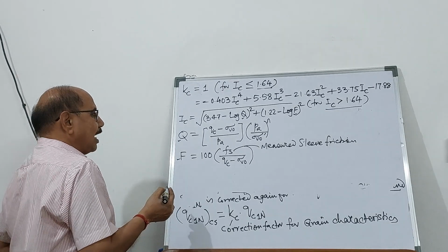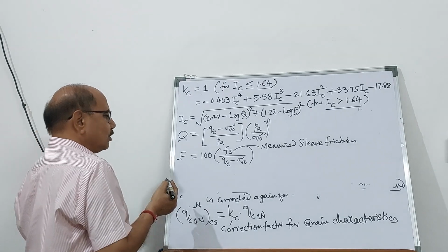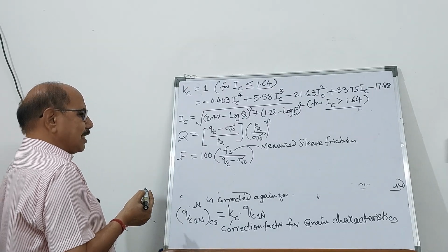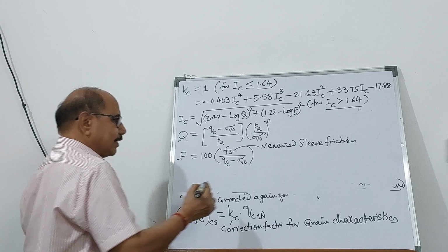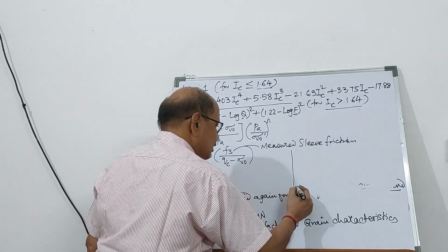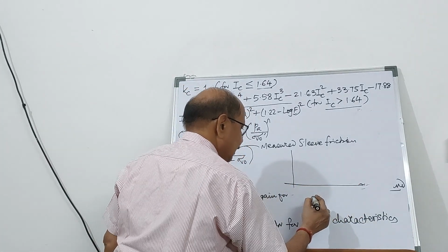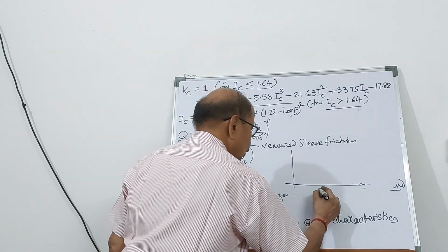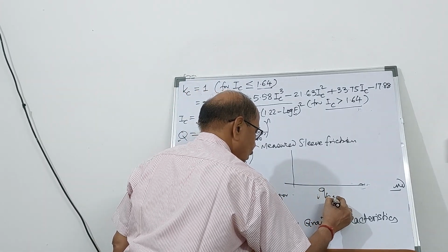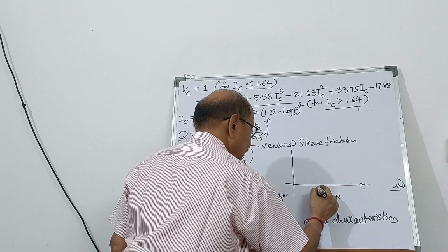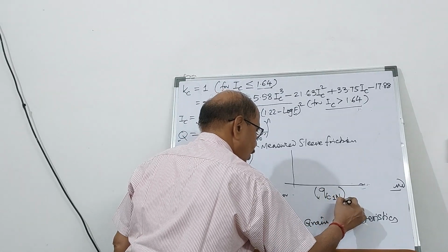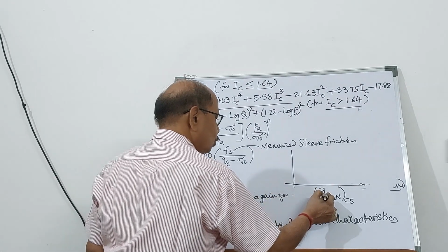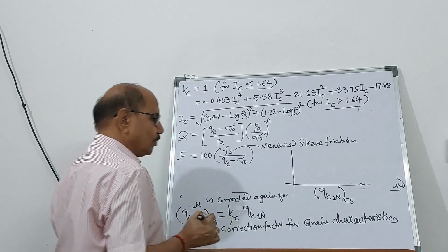So now I know the normalized value of qc for clean sand, and once you get it, if you see IS 1893 in figure 9, it is given that qc1N normalized value for clean sand, which is equal to Kc into qc1N.